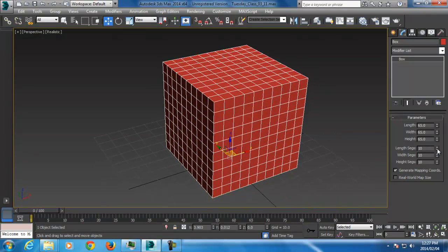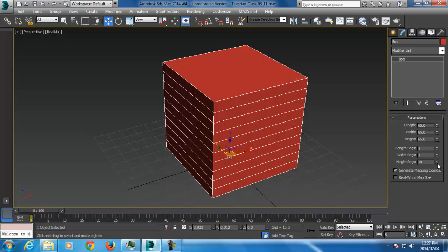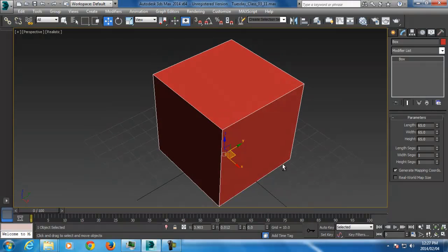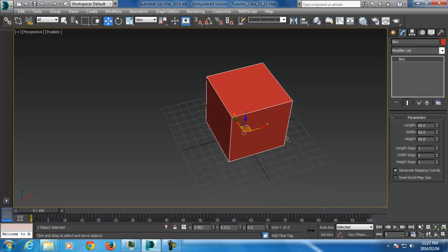So I'm going to just right click. If you want to zero anything out, you just right click on, there's a little up and down arrow. Just right click on it. It'll go away. Okay. Now, if you need to move the object, there are 3 keys you need to know, or you can go on the top here. There's a little move icon. It's 4 arrows. Next to it is a rotating arrow. And next to that is a scale arrow. If you want to, it's W for move, E for rotate, R for scale.